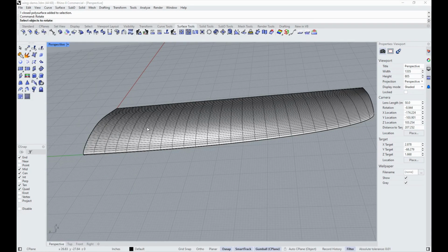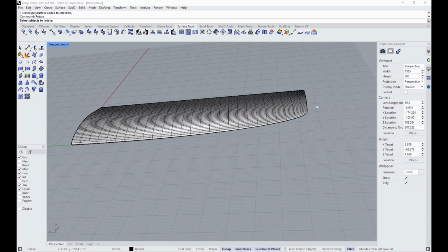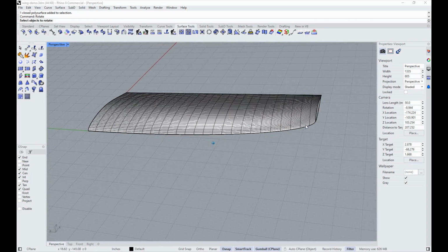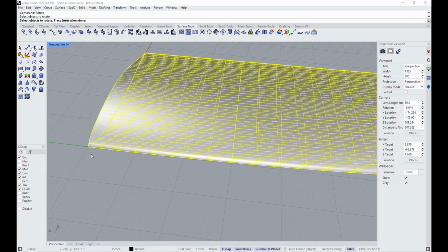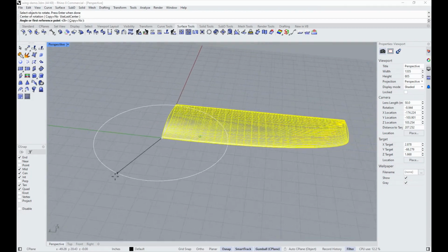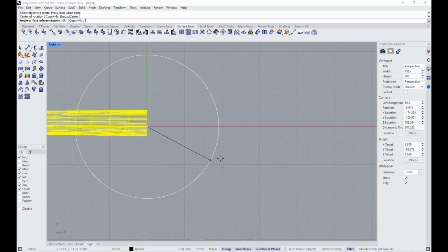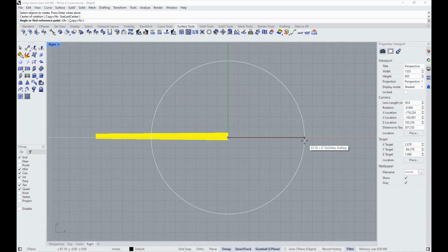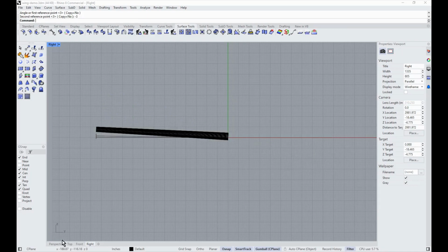So it's easier to work with this stuff planar than kick it up, honestly. Doing the washout on plane with this method isn't bad, but throw the dihedral in there, it's just a lot going on. So we're going to click on the leading edge, and then go to whatever axis is correct for that. So we'll go this way, and it would actually be negative dihedral, so we're going to do -3. So there we go.